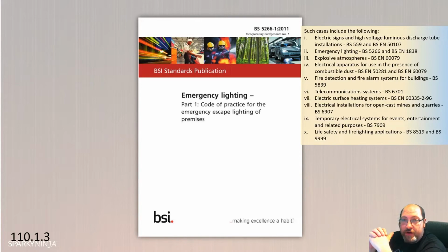But BS7909 gives us types of cabling. For example, Arctic Blue, not allowed that in BS7909. It'll have to be H05 or H07, especially if outdoors. It'll give us proper certification. For example, in BS7909, there's a requirement with inspection testing for you to verify the respective short circuit current at the final point of utilization, as well as the earth fault loop impedance. So there's additional test requirements.